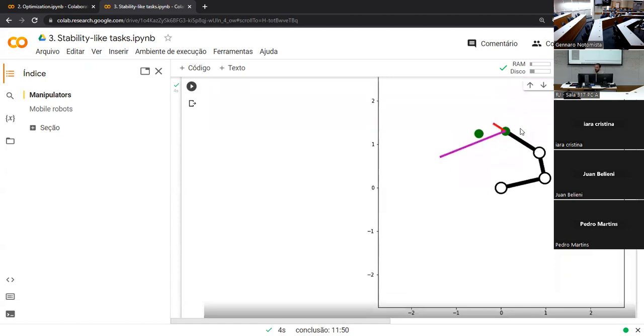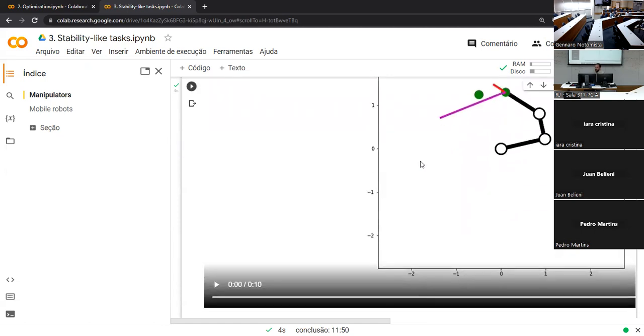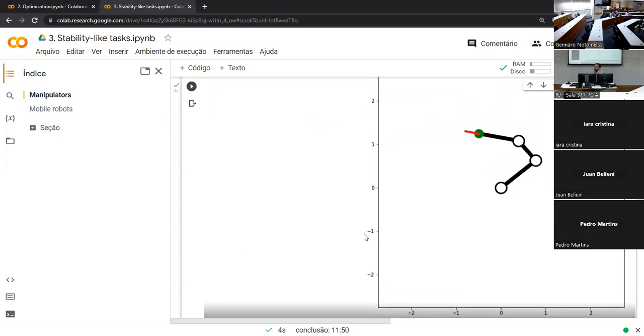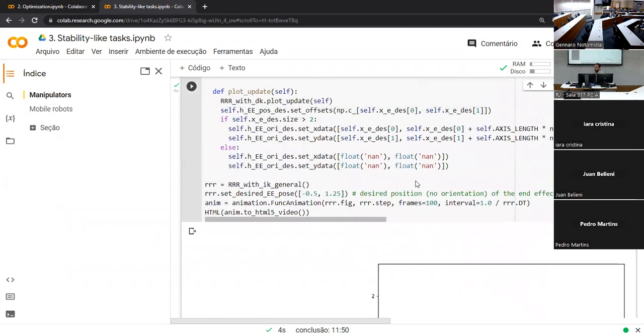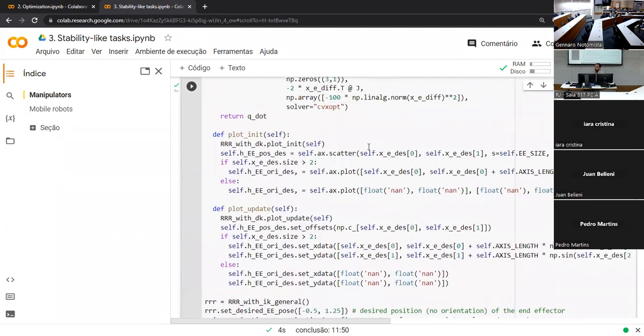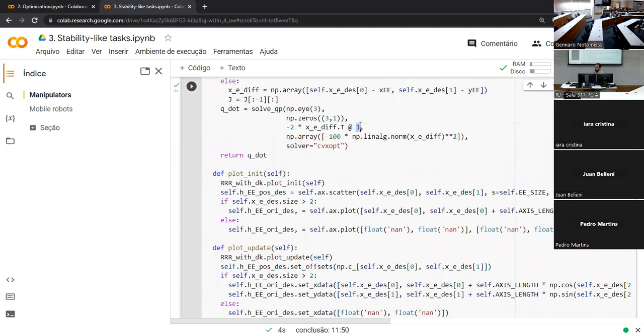You see the velocity of the end effector is this big now. Also some oscillation. These are mainly artifacts of the simulation, because the J, so all the parameters inside the optimization program, are changing based on the configuration. We have a J that depends on Q. So if the integration step is not small enough, then you get this kind of instability.